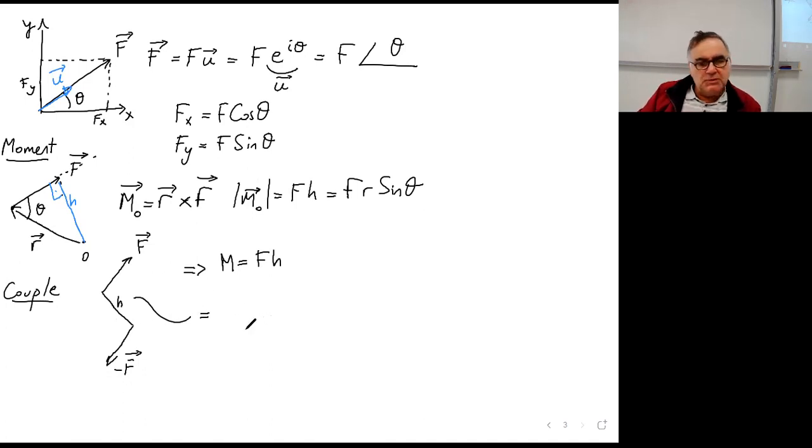And actually this whole thing can be represented, instead of these forces, by a couple like this one. You don't really have to deal with these forces because, as you see, the summation of forces here is 0. They have no effect on the system except for their couple. They have a couple on the system, but their total effect is zero.